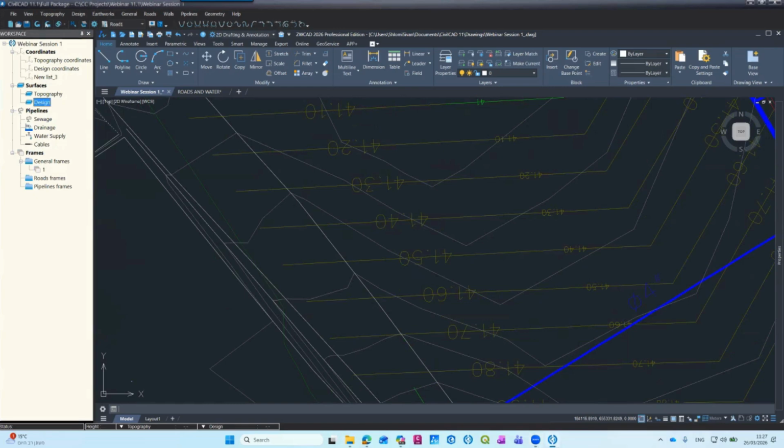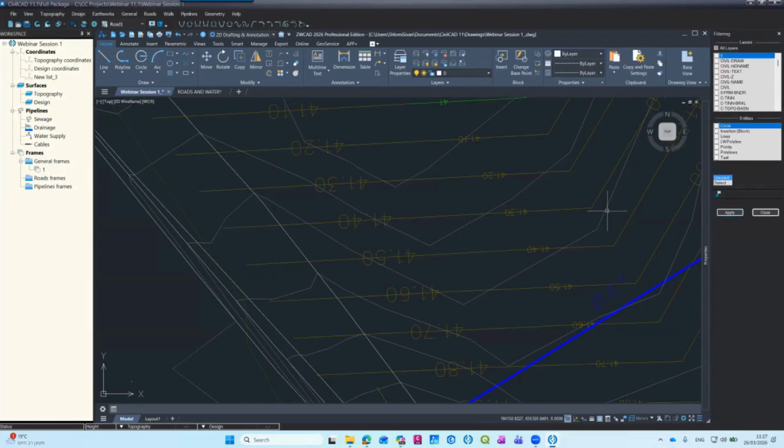So I'm going to the design surface. Again, right click, set break lines, from layers, select, for example, this one. So it says lightweight polyline, cont 20. Okay. Again, the system will scan everything.